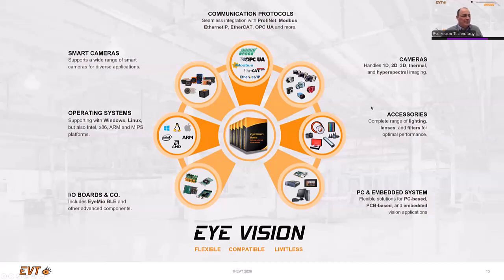But the other big advantage is line scan cameras come either with a GigE interface nowadays, if they are in the normal speed up to 16 or 20 kilohertz, and if it's faster, they come with the CoaXPress or Camera Link interface, which we both support.